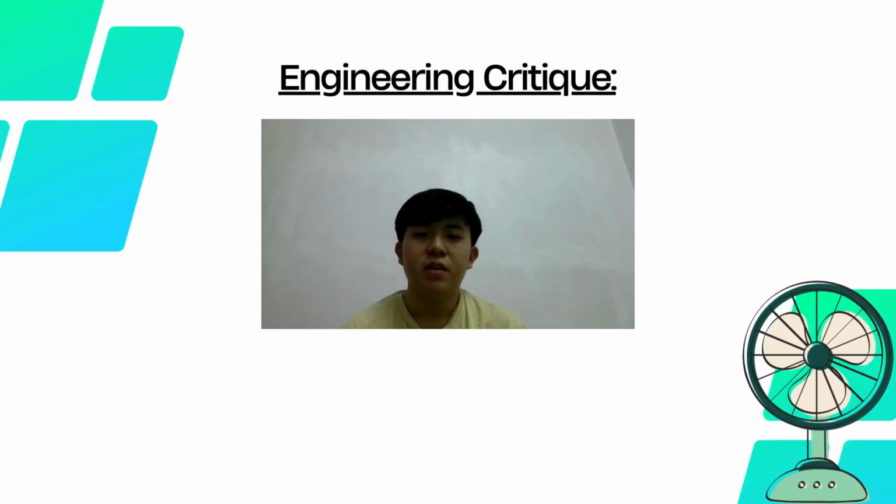After evaluating the result, I found that the theoretical model introduced some limitations. First, neglecting air resistance causes a difference between theoretical and actual stopping behavior, because in reality, airflow contributes significantly to energy loss. Secondly, assuming constant friction may not fully represent the actual condition, because friction changes with the speed and bearing condition. Thirdly, modeling the fan as a perfect circular rigid body simplifies the geometry and may slightly affect the calculated moment of inertia.